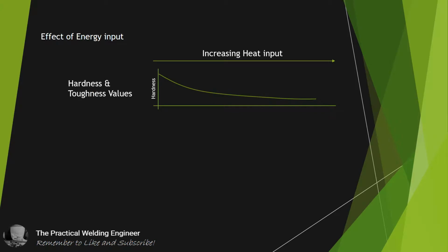Well, as our heat input increases, two big things are going to happen with our hardness and toughness values. They're going to fall away. Toughness value is your ability to withstand impact, and your hardness is the ability of the material to withstand indentation. So has the designer of your fabrication accounted for those being critical? If so, we don't want a runaway value within our heat inputs.